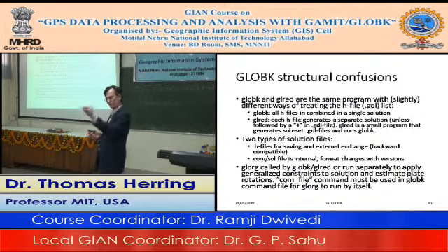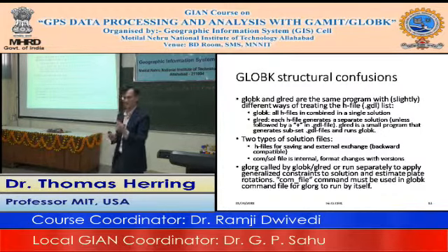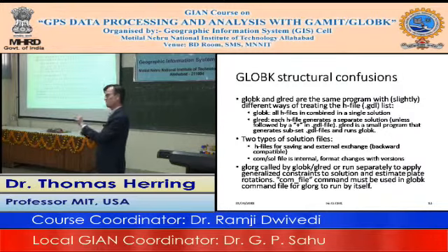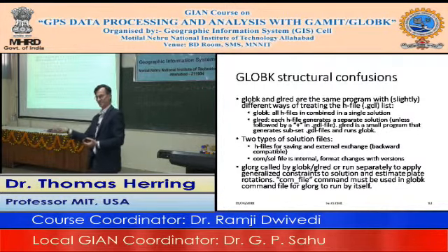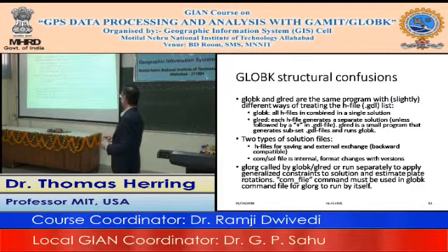So if you want to run GLOBK by itself, you need to have that COM file, and you need to have the SOL file that goes with it. And you can do that, but if you upgrade GLOBK to a new version, there is a chance that the COM file you generated with the last version will not work anymore. So we typically also save the GLSave program from each version so that you can use the old version of GLSave to write your COM file out as a standard full binary H file and then use it in your new solution. So we try not to make this too hazardous.